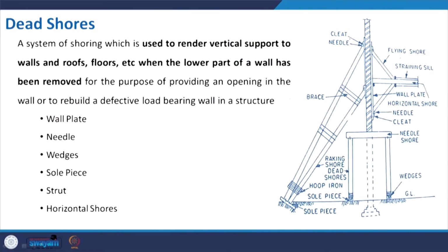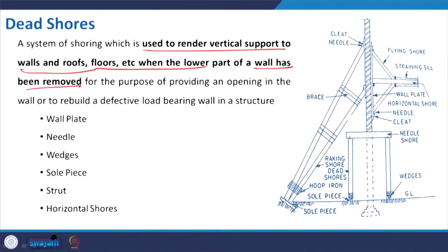Coming to the dead shore. Dead shore is basically used to render vertical support to the walls, roof, floors, when the wall has to be removed or maybe some foundation is to be extended. So, this is the extended picture, where it is a combination of all.